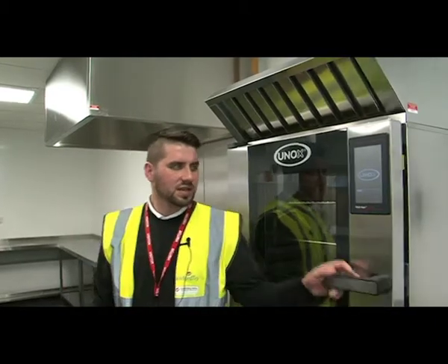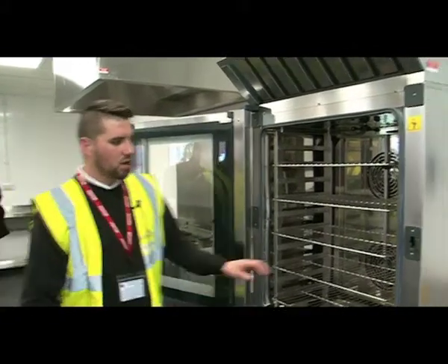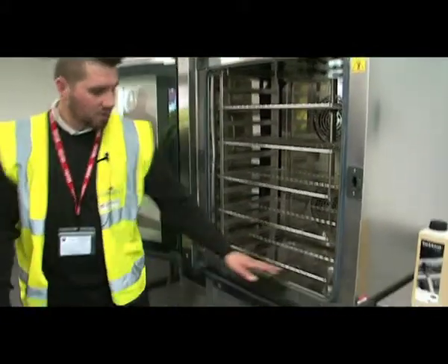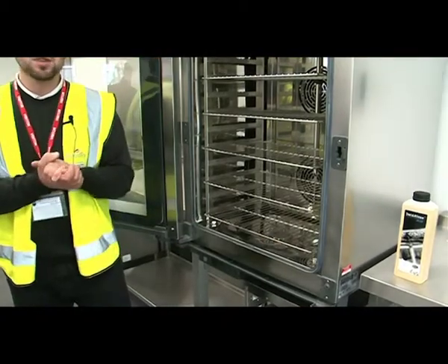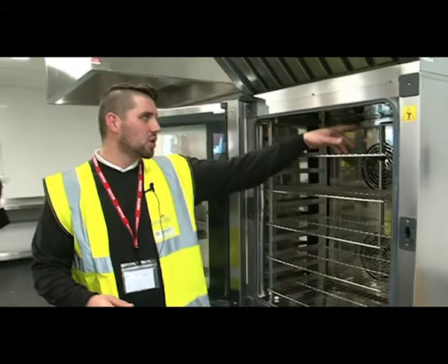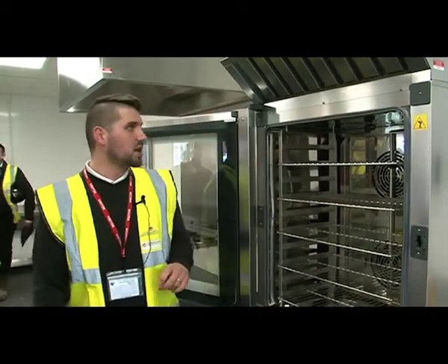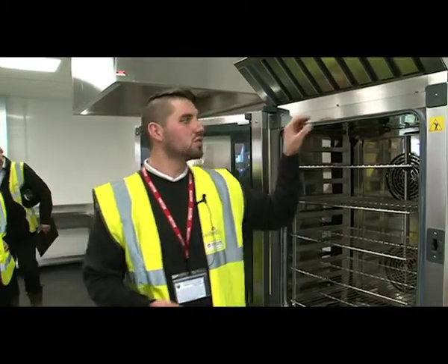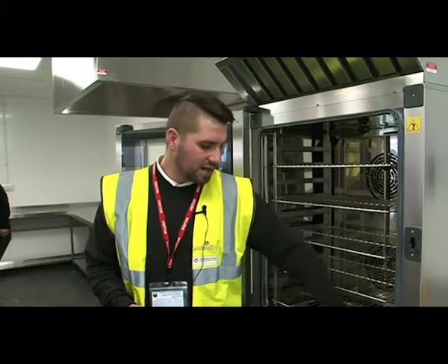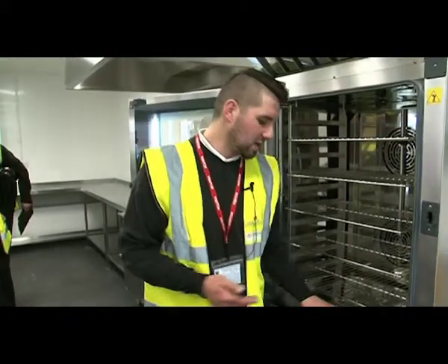Quickly into it, so it's a 10 tray combi oven, 1-1 Gastronom with a multi-point core probe inside there. It's a self-cleaning oven with the rotor arm at the top here, and there's also rotor arms behind the fan guard that cleans. There's a couple of manual elements of cleaning that you need to keep on top of. One, it's the gasket around the chamber. Just make sure you're lightly wiping that down just with warm water.